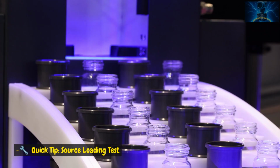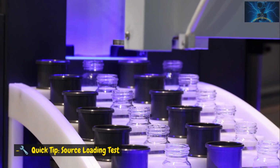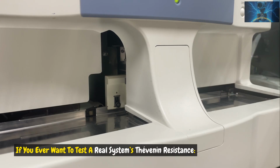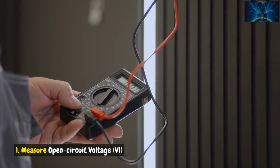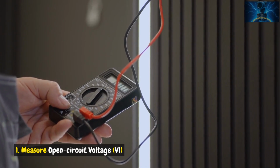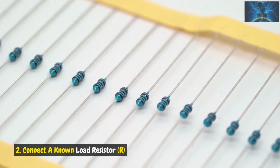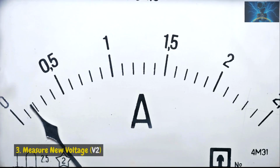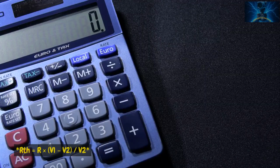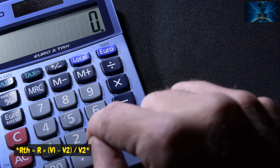Quick tip: source loading test. If you ever want to test a real system's Thévenin resistance: 1. Measure the open circuit voltage, V1. 2. Connect a known load resistor, R. 3. Measure the new voltage, V2. Then solve: RTH equals R times (V1 minus V2) divided by V2.